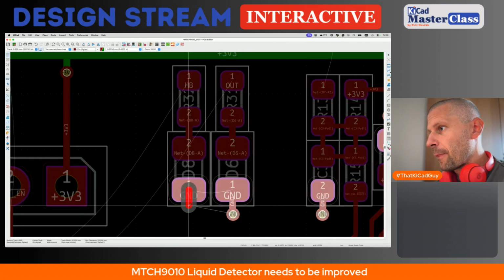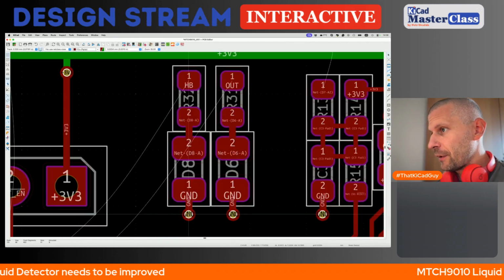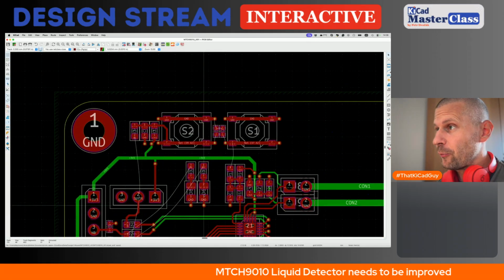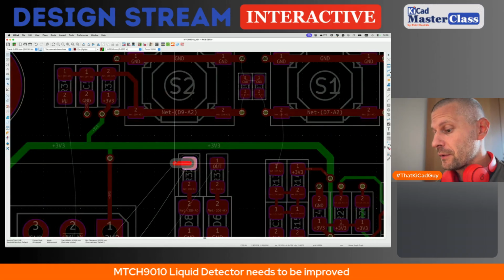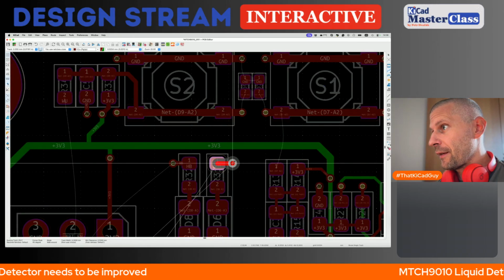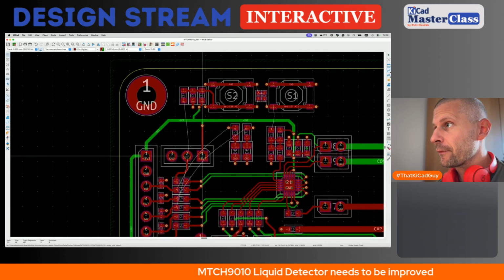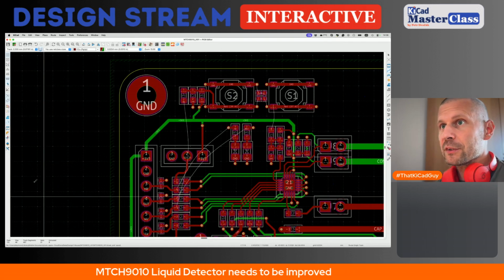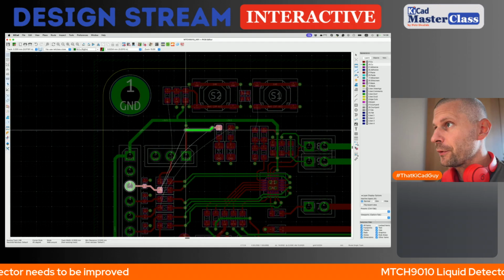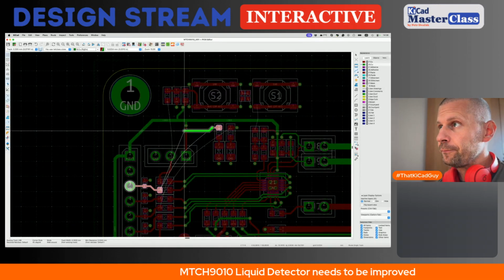I'm placing the ground vias next to each other to be in line, because this way provides me with some cleanliness, and I want my boards to be clean and neat. So now we can switch to the bottom layer and route these two signals.